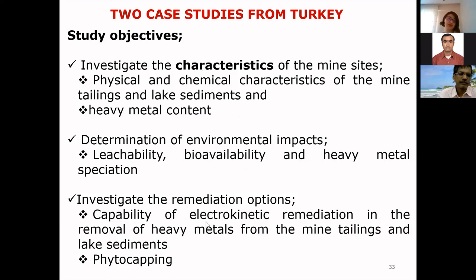In these projects, our study objectives were to investigate the characteristics of the mine sites. For this purpose, we determined the physical and chemical characteristics of the mine tailings and lake sediments, and also we determined the heavy metal content. And we determined the environmental impacts. For this purpose, we did some leachability tests to understand the bioavailability and heavy metal speciation.